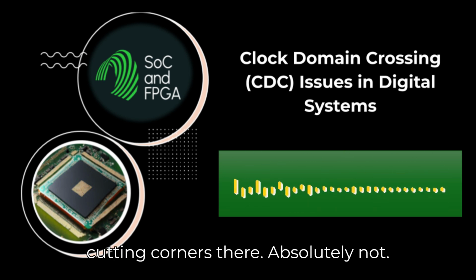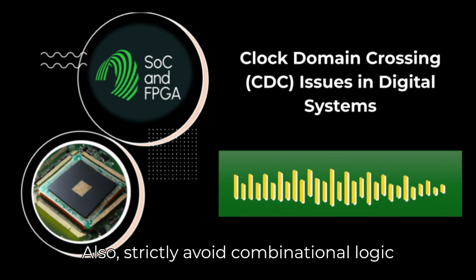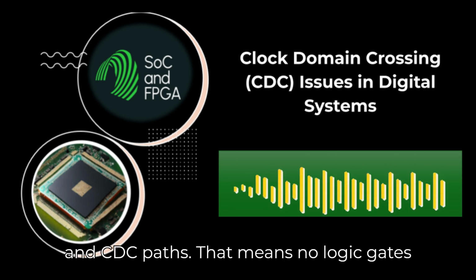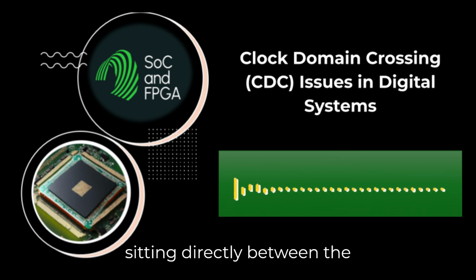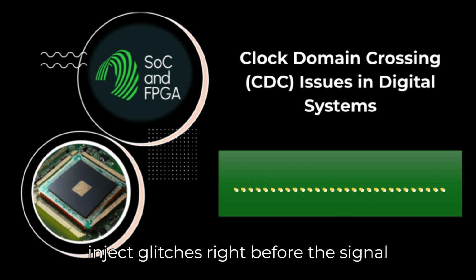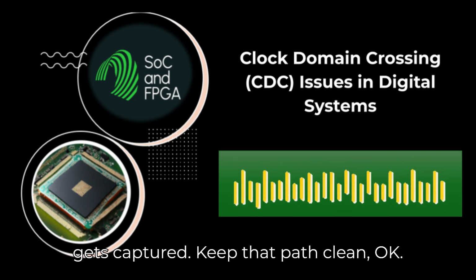No cutting corners there. Absolutely not. Also, strictly avoid combinational logic in CDC paths. That means no logic gates sitting directly between the synchronizing flip-flops where they could inject glitches right before the signal gets captured. Keep that path clean.